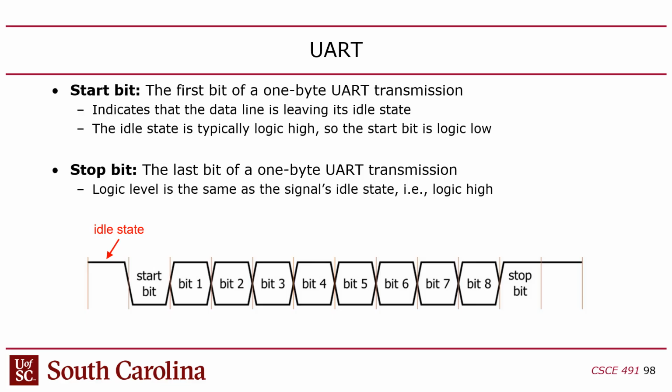And then when you're done sending, you would just have a stop bit or stop bits, where the channel just goes high. Basically, what the stop bit does is it guarantees that if you're sending consecutive words or consecutive bytes, you know that you're going to have a falling edge for the start bit. So the purpose of the stop bit is to reset the channel, get that data high, so then I can wait for it to go low to signify the start bit. Does that make sense?